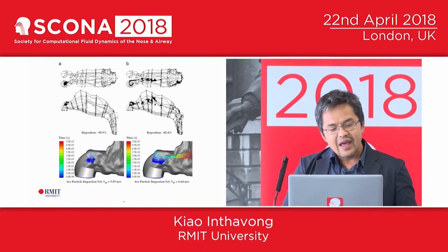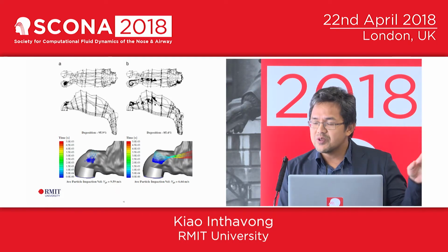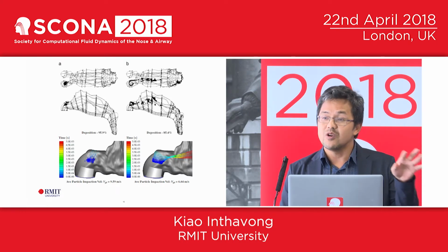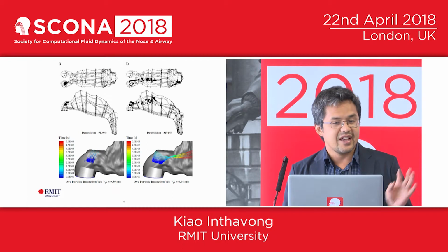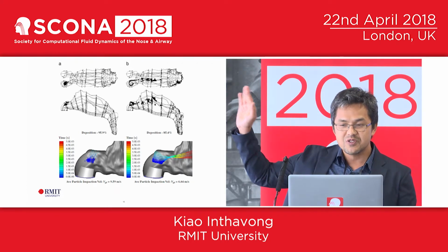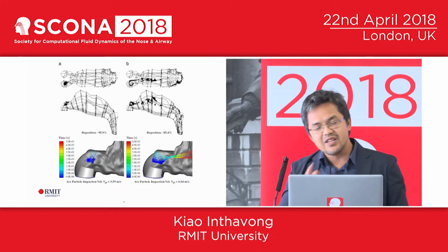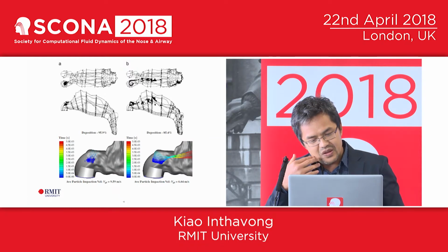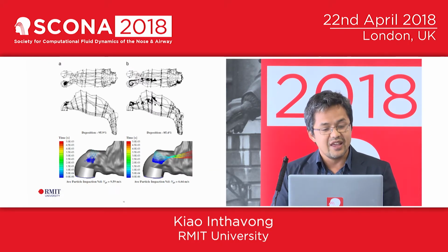Okay? And as we move up towards the olfactory region, the presenter before was talking about how there's not much flow up there, and that's from our engineering perspective for a reason. You want some flow to go up, but you don't want the majority of the flow to go up, because if it transports those particles, then those particles will shoot straight into the olfactory nerves and damage the nerves. So particulate matter and particles that are dangerous are filtered out firstly through the nostrils, and then by that lower flow rate up to the olfactory region.